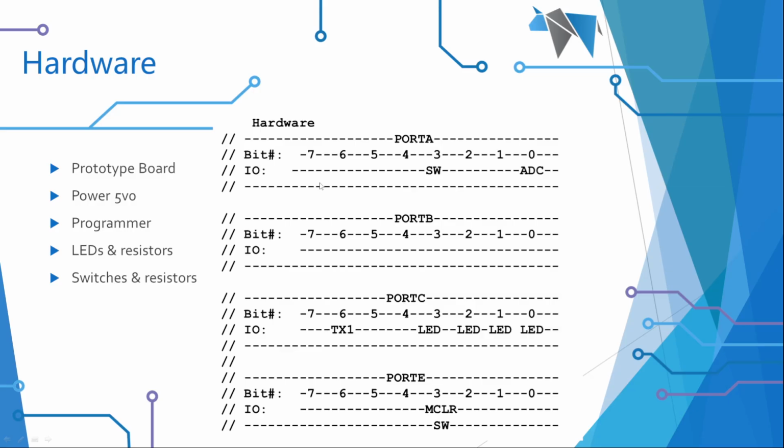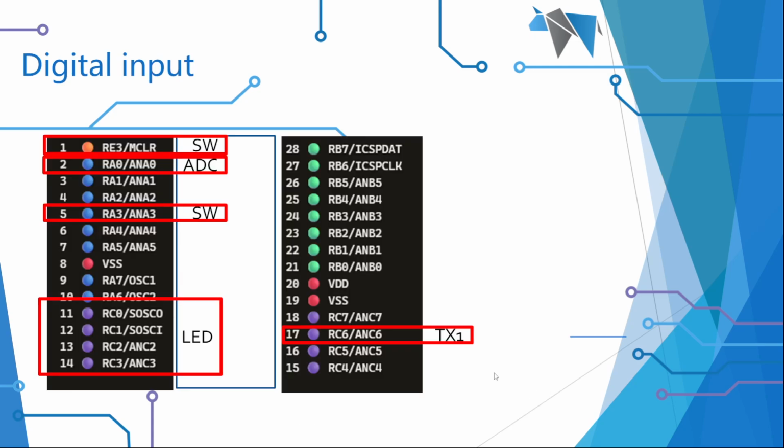In terms of hardware, let me just bring the pen up. I've actually got a new connection. It's on port C6. That's where I will be transmitting data, called TX1. TX1, remember that? Transmit. So it's down here, on the right-hand side of the chip. It's this one here. And this will send data out, and we're going to pick that up in the USB TTL converter.